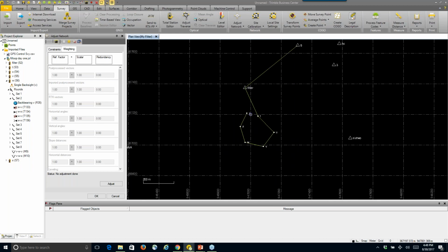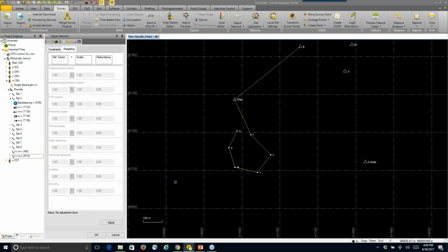The value that you have for point Y is as good as it's going to get on an open-ended traverse, because the computation engine is already using the mean angle records of the observations, and when you get to Y, there's no other point to go to. I may prove myself wrong here and have a slightly different answer, but you could compute this least squares.